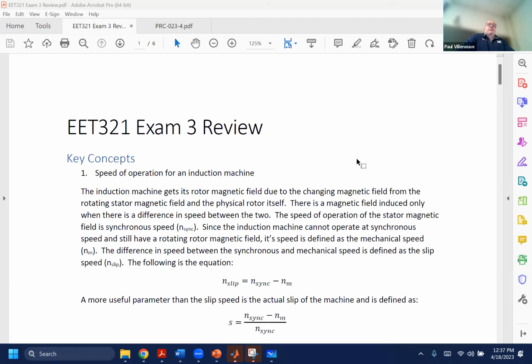3 big voltage regulators, like where the police cars are on A3, on the way to the Ave, we have a section with 3 big voltage regulators. Yeah. If it was one of those poles, those regulators would probably not be on the 46 kV system. They're usually on distribution circuits. But again, it's very common that you have 2 overhead lines that share a pole, just because you can't run 30 poles on the side of the road. It's just not practical. So it probably took out a section of the 46 kV, and that's my best guess.